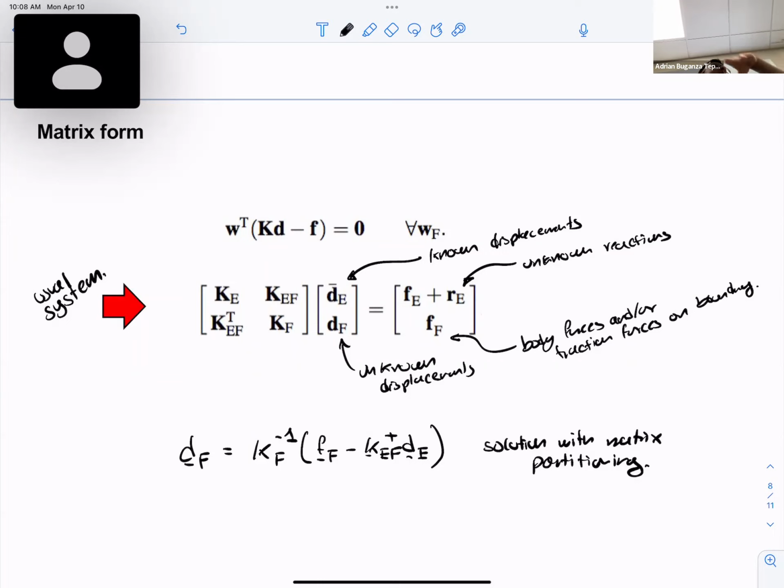Then you have the weak form. You introduce your finite element discretization. Again, the only difference with respect to the heat transfer is that now you're doing sort of two heat transfer problems at the same time. Once you plug in the finite element discretization, you do a little bit of algebra to take out the sums and the nodal values. Then you end up with the definition of the stiffness matrix and the force vector, which involves integrals of the gradients of the shape functions. Once you have the element stiffness matrix and element force vector, you can assemble into the global stiffness matrix and global force vector, and then you can do your matrix partitioning and solve. So same flow.